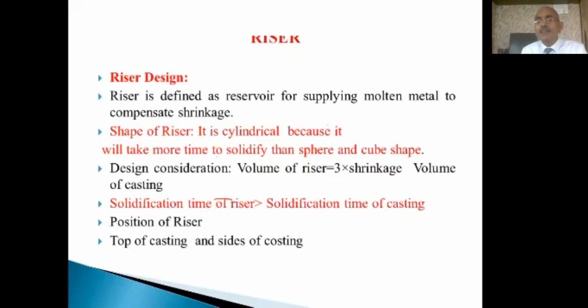And the solidification time you should note down. The solidification time of the riser should be greater than the solidification time of the casting. First the casting should get solidified, then the riser. Position of the riser: you can keep it on the top of the casting or at the side. You can keep it on the left side or the right side of the casting. These design considerations are better.